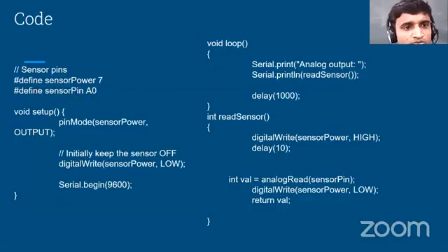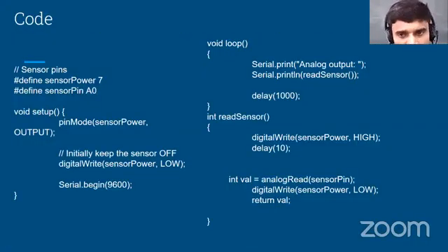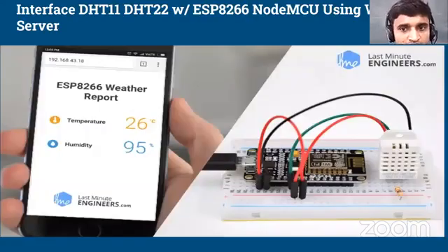In this simple code I have written, you define the pins and define the converter, because you want to say that this is my pin where I connect my sensor. Based on the sensor, you define the values and capture the data from the sensors, and you will see the result here in the serial monitor. Same thing, this is a demo code, same thing for humidity and temperature.